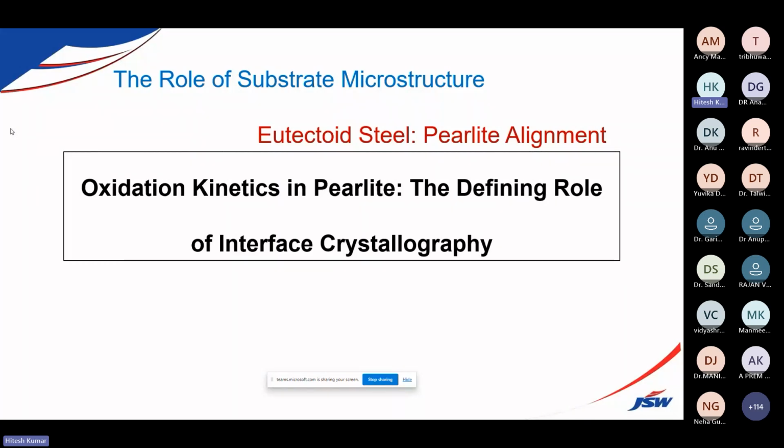Those are the major interstitial atoms which sit in interstitial sites of the iron unit cell, and they are used to improve some of the mechanical behavior of the material. If those are in ppm, the material has a single phase, that is ferritic, BCC only. BCT will not be possible without interstitials.